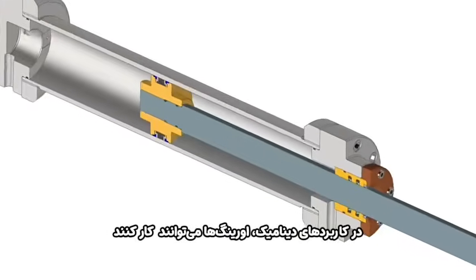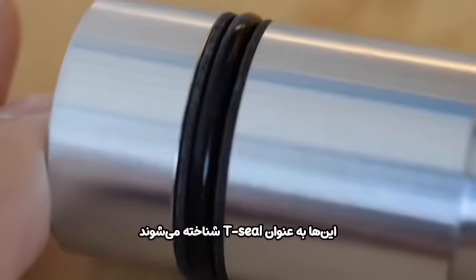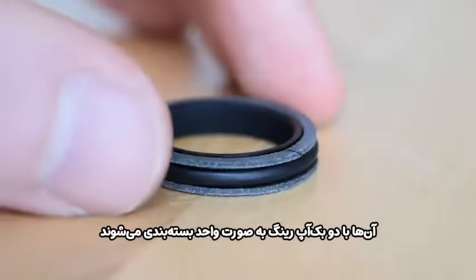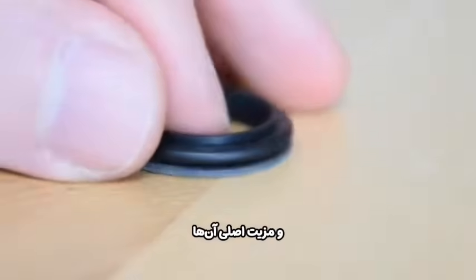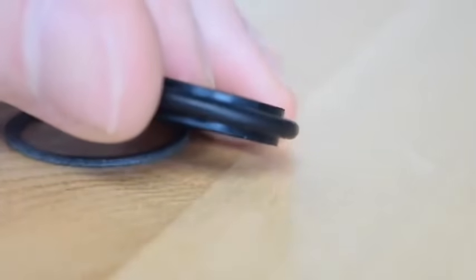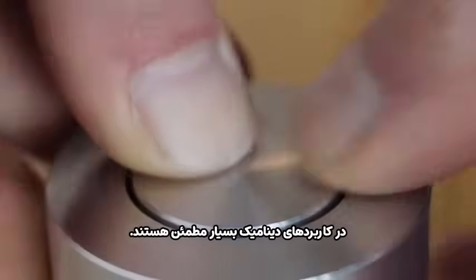In a dynamic application, O-rings can work, but there are much better options to consider. This is called a T-seal, and they are specifically designed for dynamic applications. They are packaged with 2 backup rings as a unit, and their primary advantage is that they have a wide, flat bottom to keep them from rolling around in the groove. They don't cost much more than O-rings, and in our experience are very reliable in dynamic applications.